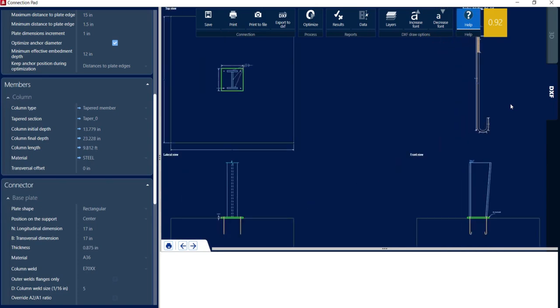So that's all from my side. This is the normal workflow for this entire pre-engineered building analysis and design, including the modeling. Now, this is a generic example. The pre-engineered building might have some special shapes, special kind of loading. For example, the crane loading. In some pre-engineered buildings, there are crane loadings.